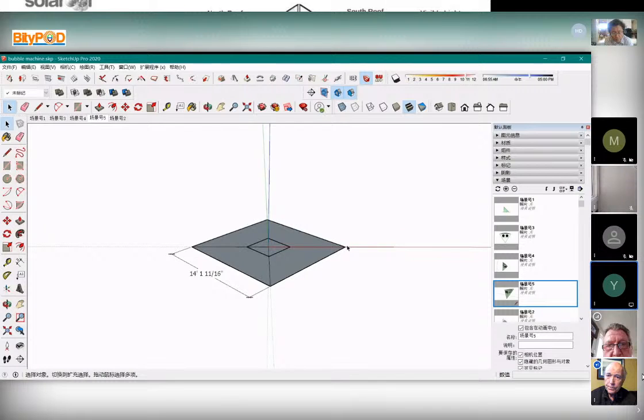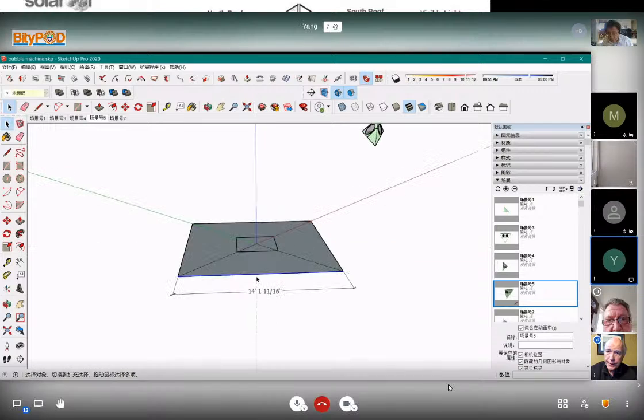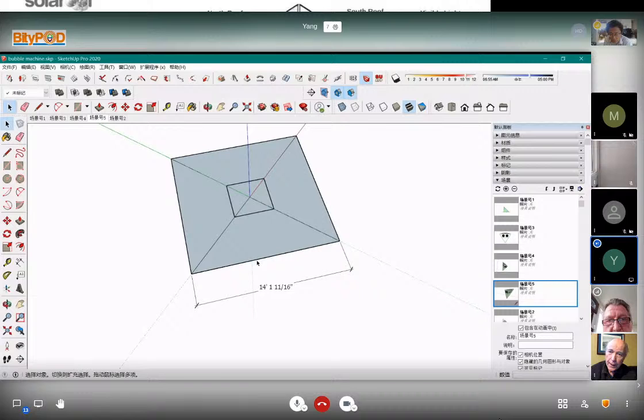I mean this one. Yeah, 14.14, just following along the axis, right? We're going to stay on the red axis. Is that the Y or the Z? The Y, yeah, the red line. So we go from the outside corner, the tip, and make a line, not vertical but horizontal, right on the axis. The length is 14.14. So make that distance from the corner along the axis, because that's our origin for the arc.